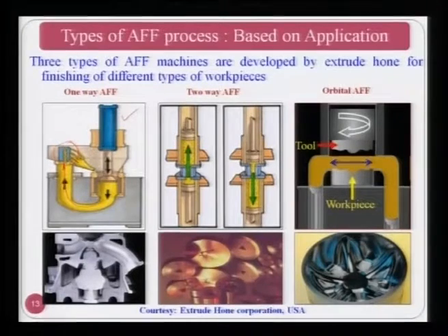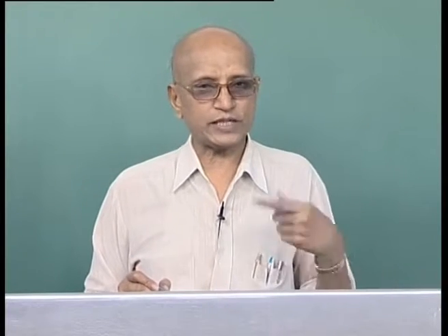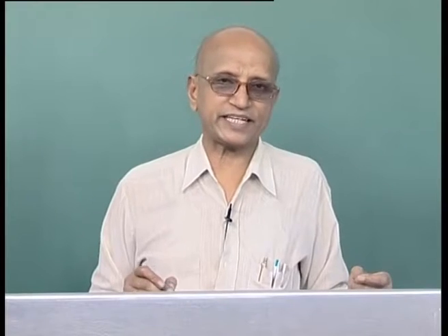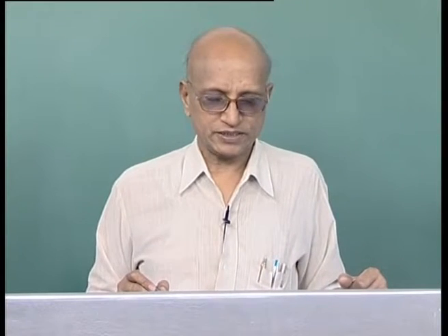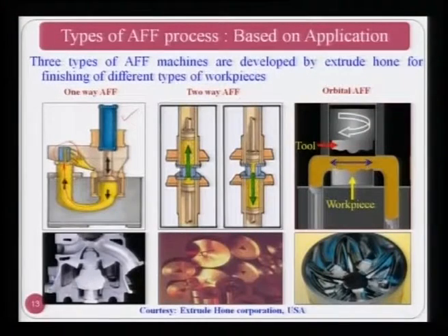is coming out and the medium consists of fine abrasive particles, these fine abrasive particles will come in contact with the workpiece surface. So, what I have shown in the earlier slide, in the same way they will shear the peaks of the workpiece surface, and surface roughness will be reduced substantially. Now, after it comes out of the workpiece surface, it is collected and recirculated the same way as shown by the arrows over here.